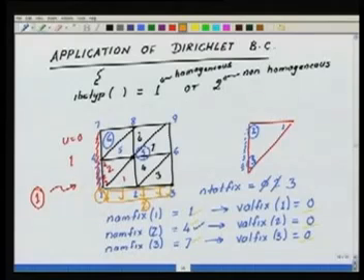And we should not get confused, thinking that from one side I am getting a load contribution and from the other I am getting a displacement contribution, because remember, these things are defined only on the edges. So with all this done, we should now be able to assemble the global stiffness matrices and the global load vectors, apply the Dirichlet boundary conditions, and solve the problem. That should not be a problem as far as the simple problem that I have taken.